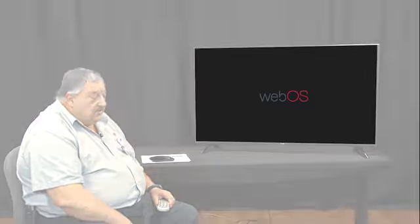The delay is because we've changed something, so it has to reload the WebOS operating system with that new information, and it has to dump the EDID data down into the EEPROM for handshake through the HDMI port. Well, of course, that takes some time.